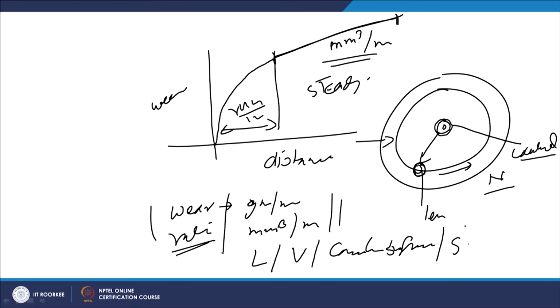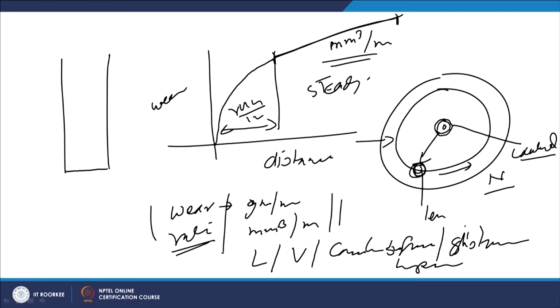the sliding distance, the temperature realized. We know that during the sliding there will be continuous rise in temperature. So sometimes measuring the temperature of the wear pin at different locations also helps in explaining the wear behavior. So normally we insert thermocouples at different locations, at increasing distance from the sliding interface, like say at an interval of 1 mm, and then we plot, like say 1, 2, 3, 4, 5 mm, 5 different thermocouples inserted at 5 different locations, increasing distance from the surface.